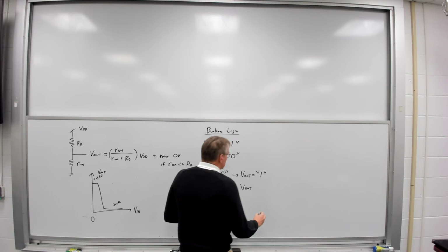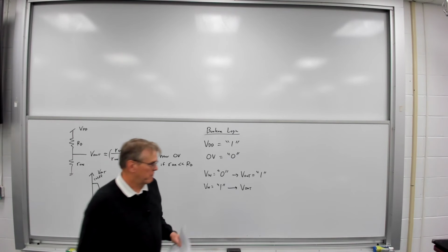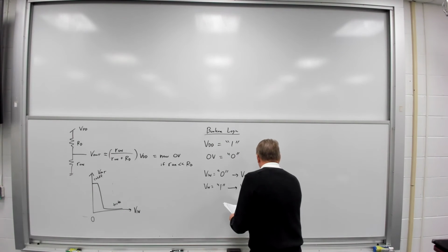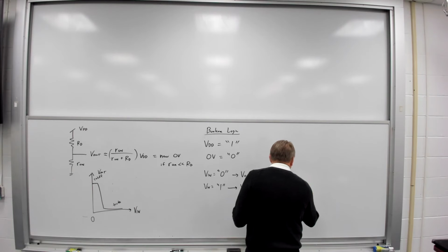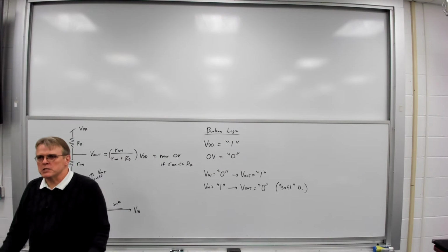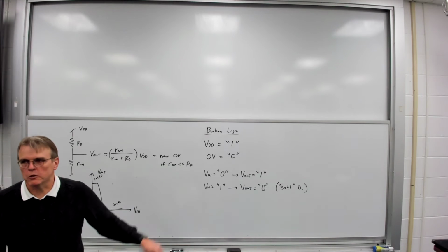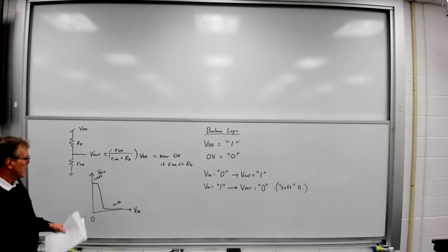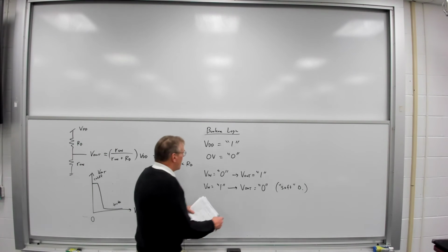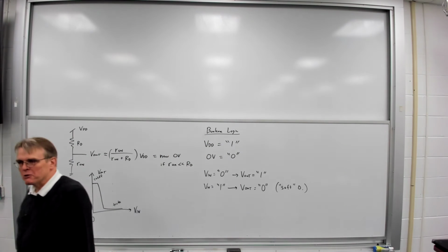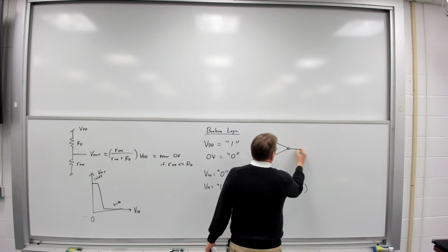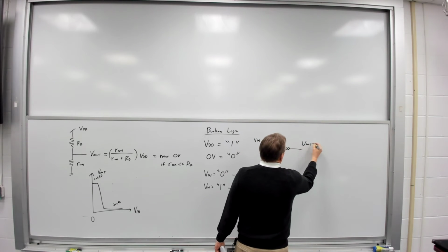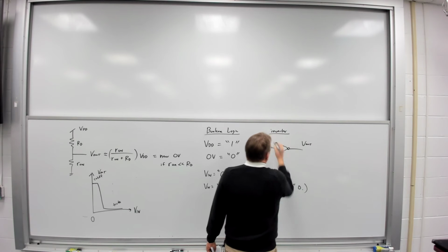then V out is, we call it a soft logic 0, approximately a logic 0. So it's a soft logic 0. It's not really all the way down to 0 volts, but it's going to be close enough. Close enough where a digital circuit will interpret it as a logic 0. So we look at this thing, and what is this logic function? Those of you who took digital systems, what is that? That's an inverter. Yeah, this is an inverter. Problem is, it's not a very good inverter.